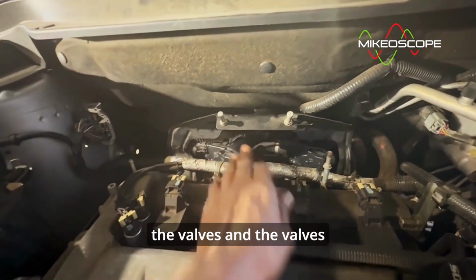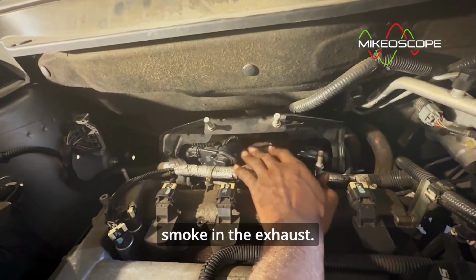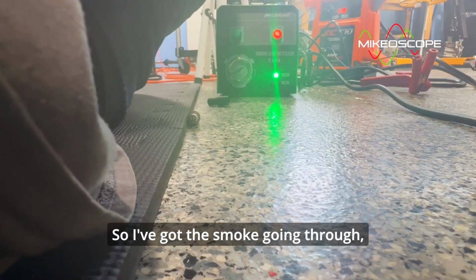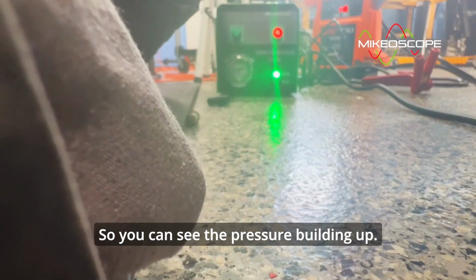Okay, so once it gets to the valves and the valves are closed again, it should build pressure. It should not be able to go through the valves and through the exhaust. We should not see any smoke in the exhaust. Okay, so let's turn the smoke machine on. So I've got the smoke going through all the way to the valves. You can see pressure is building up a little bit, indicating the valves may be closed, probably closed, so you can see the pressure building up.